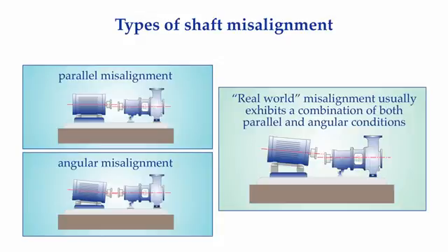It is important to understand that shaft alignment, in its purest definition, is the process of aligning the center lines of rotation with each other, which are shown as the dashed red lines in the illustrations. Be aware that certain points along the length of the shaft may or may not be concentric with the center line of rotation of that shaft. In other words, you might have a run-out condition that could be overlooked or cause some grief when attempting to align the machinery. How to find and correct any run-out problems will be covered in another tutorial.